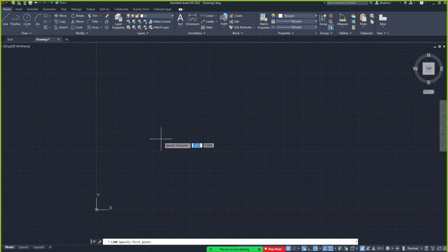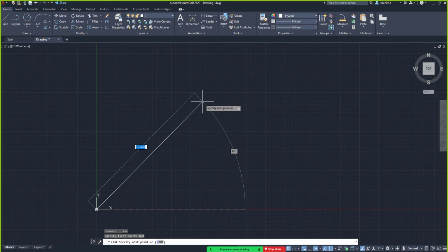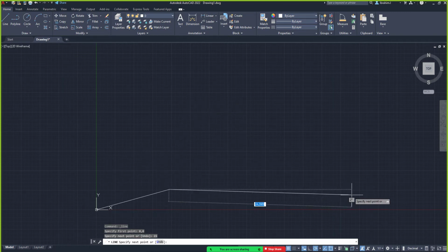first point. We are using our 0 origin, 0, 0. I just click on 0 and then 0. This is called absolute coordinates. That means you have a dimension in mind. You always want to enter into it. So you have your degree. You can specify exactly what you want. If it's 15 degree, you can do all these measurements directly from the beginning, and then you continue.